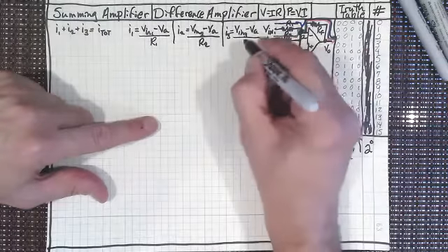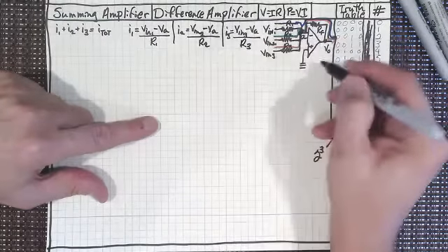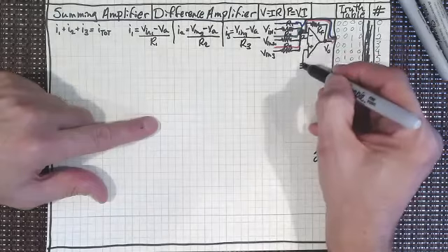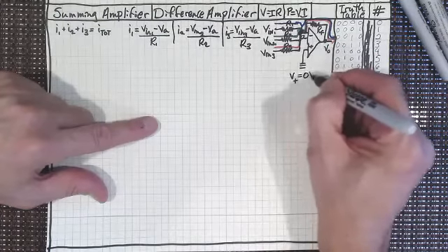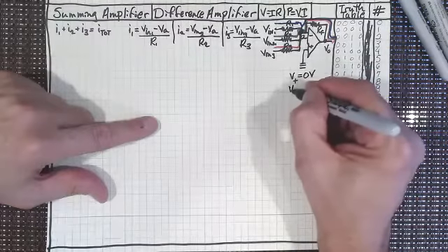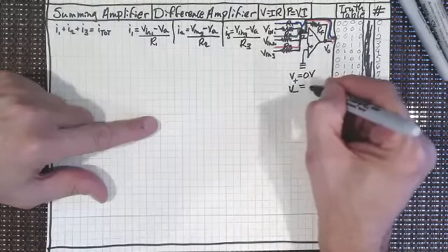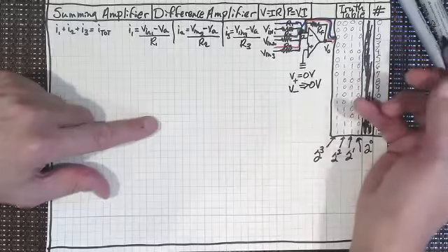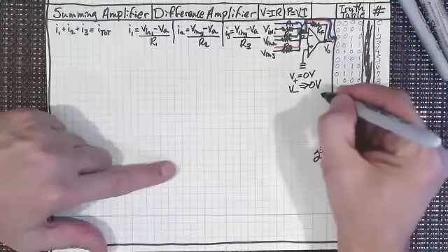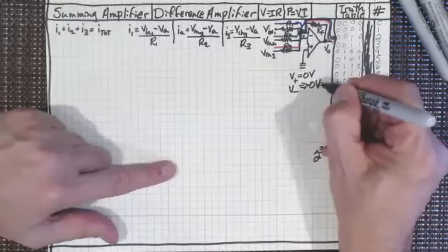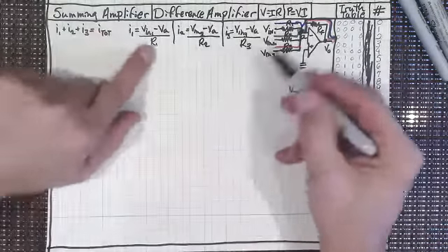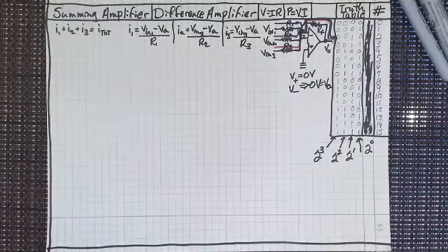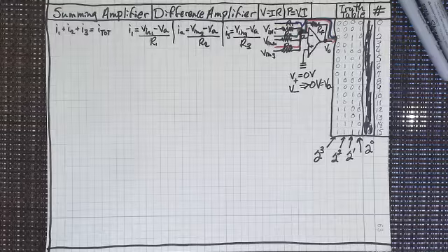I think everybody, because we've already done this one time before, is going to say, well, if this is 0, if V plus equals 0 volts, then I know that V inverted should equal 0 volts too, shouldn't it? So we know that VA is going to be 0. And we can include that later on in our analysis. Right now, I'm not sure we really have to do that.